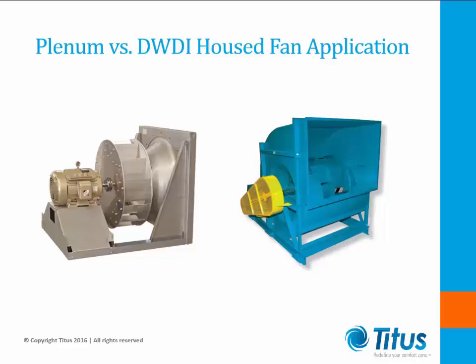Some other characteristics of our fans may concern outlet flexibility. Plenum fans serve to pressurize the entire fan plenum, allowing for multiple duct takeoffs from the air handling unit. Additionally, these openings can be tailored to match virtually any duct configuration, whether it be rectangular, round, flat oval, or with a bell mouth fitting, just to improve the acoustic and optimize pressure drop performances.